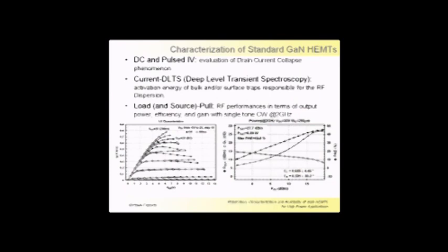We developed a standard technology in cooperation with the National Nanotech Lab in Lecce, and these are measurement results of such a standard device. The measurements have been carried out here in this department using DC and pulsed IV setup, current DLTS for spectroscopy, and load and source pull measurement setup for the RF power.